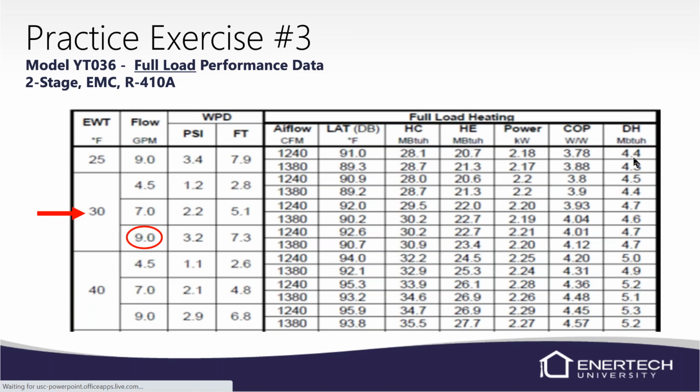at that water temperature. We normally would recommend that you just disconnect it and not run it with the desuperheater on. I know this YT unit has a switch on it, so you can just flip the switch and it turns it off. Some of the older units, you will have to take the Molex connector off the pump to disconnect the power to the pump. But we do normally say, make sure you're in second stage and desuperheater off. But if for some reason you leave it on, some of these YT manuals will let you know how many BTUs the desuperheater is robbing.